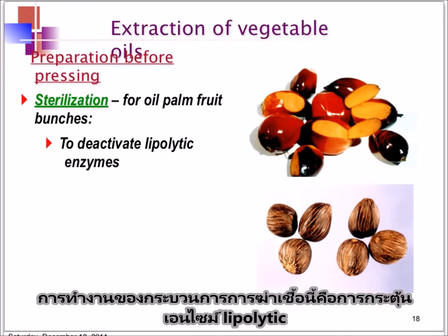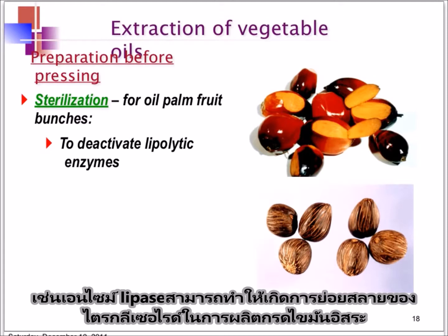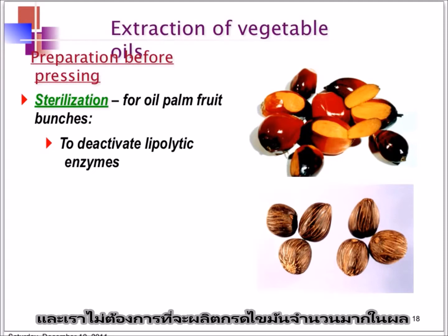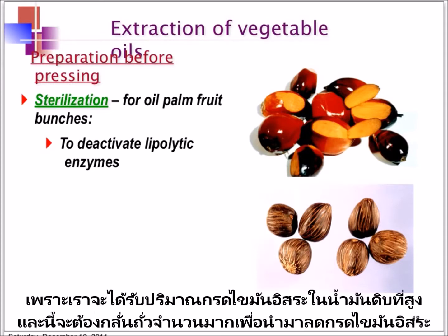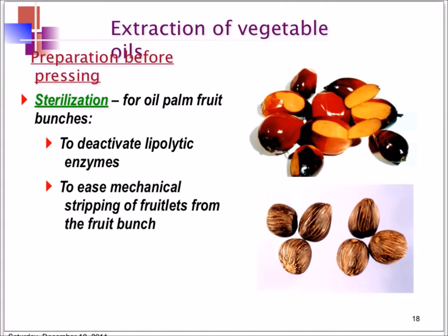The function of the sterilization process is to deactivate the lipolytic enzymes. In the fresh fruits, the presence of lipolytic enzymes such as lipase can cause hydrolysis of the triglyceride to produce free fatty acid, and we don't want to produce a lot of fatty acid in the fruits, because you can get a high amount of free fatty acid in the crude oil, and this will require a lot of refining later to remove the free fatty acid.